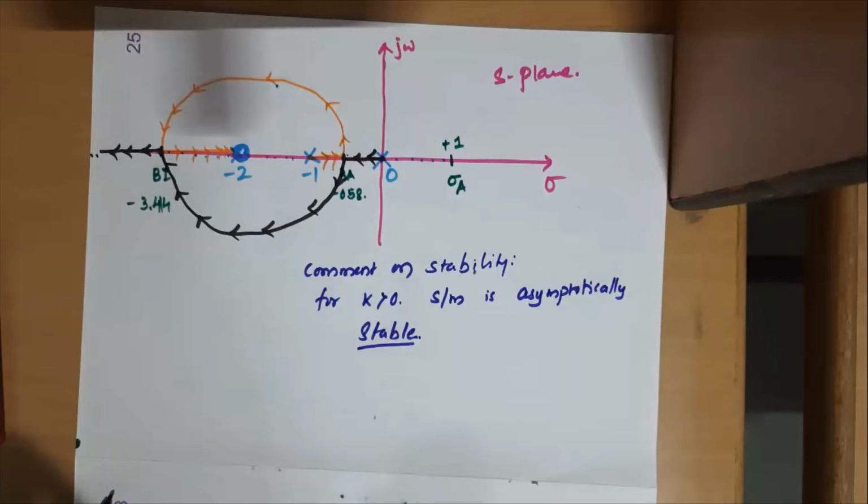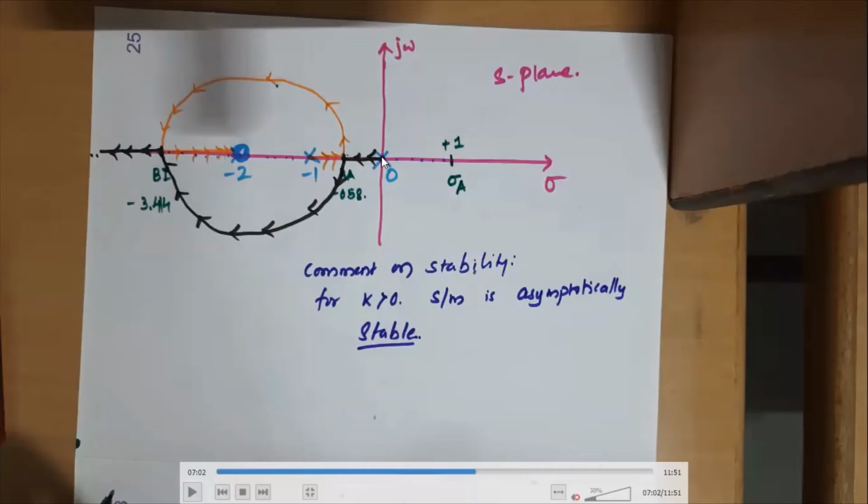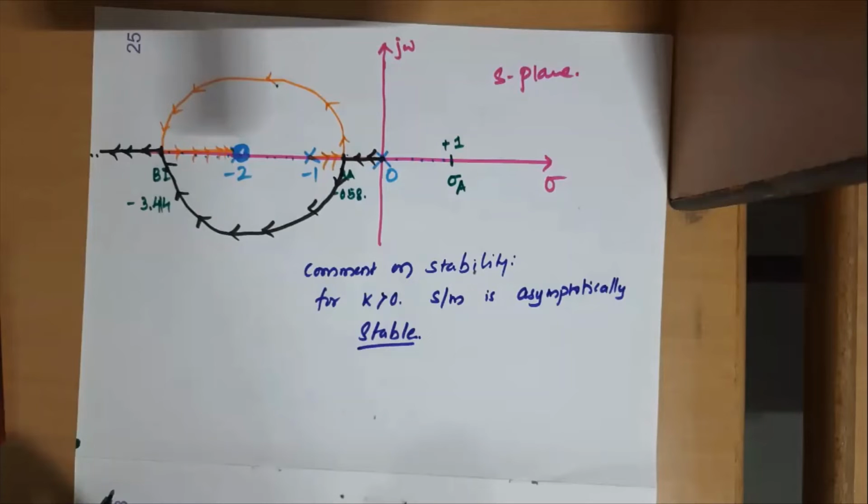But someone may cross question you at k equal to 0, it has a pole at imaginary, what does that mean and all. So let us mention on the safer side it is stable only for k greater than 0, and at k equal to 0, it is obviously critically stable. But no practical system is tested for its stability at gain equal to 0. That is another way of interpretation. So I hope it is clear. Anybody has any doubt with stability?